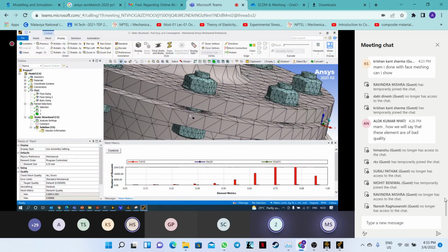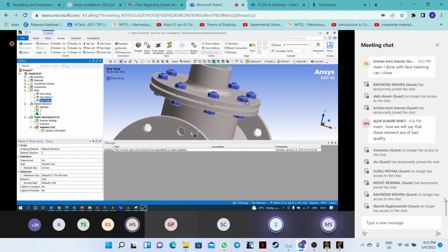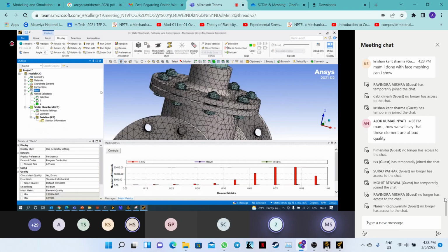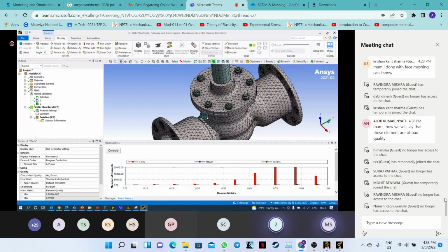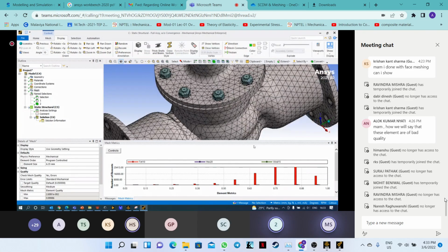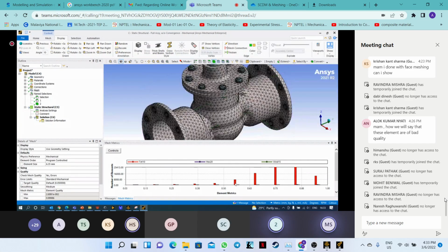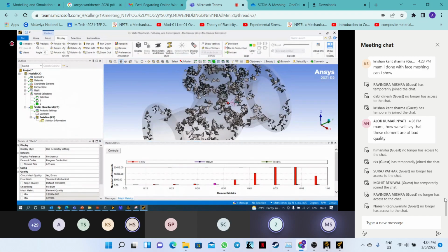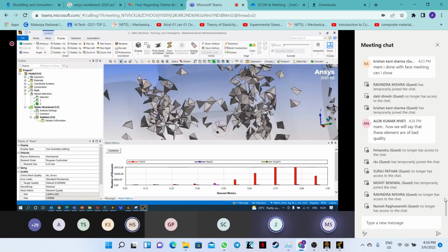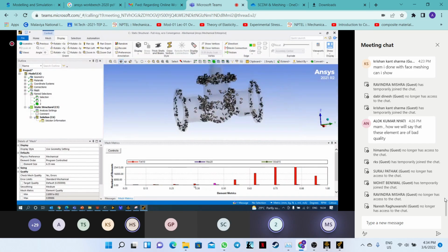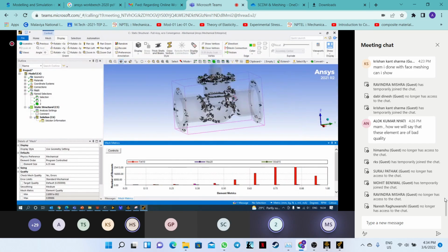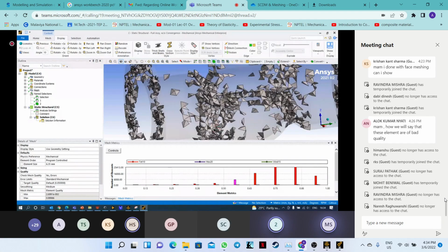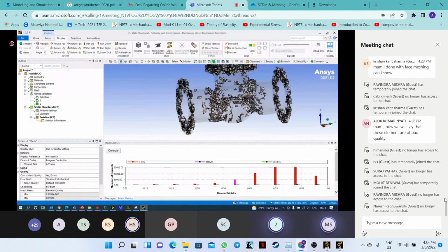So you can make use of either body sizing, or you can give certain surface sizing and try to get a proper kind of mesh generated there, right? Now still you can check where your poor quality elements exist. First thing is this region you're seeing is still there, and of course it is selecting the same regions. So let's work on this region.